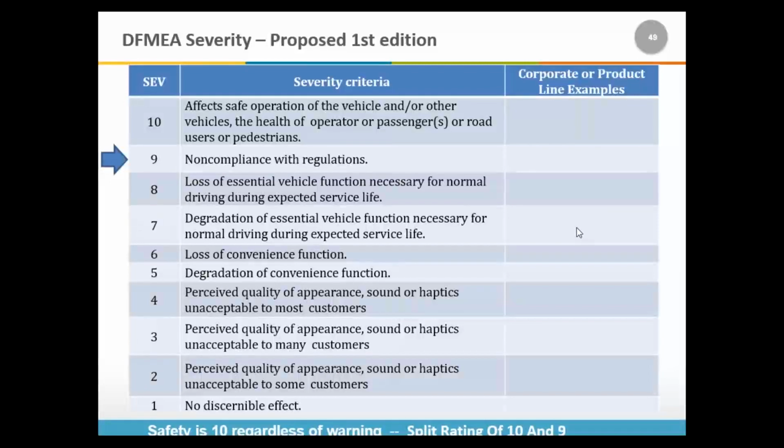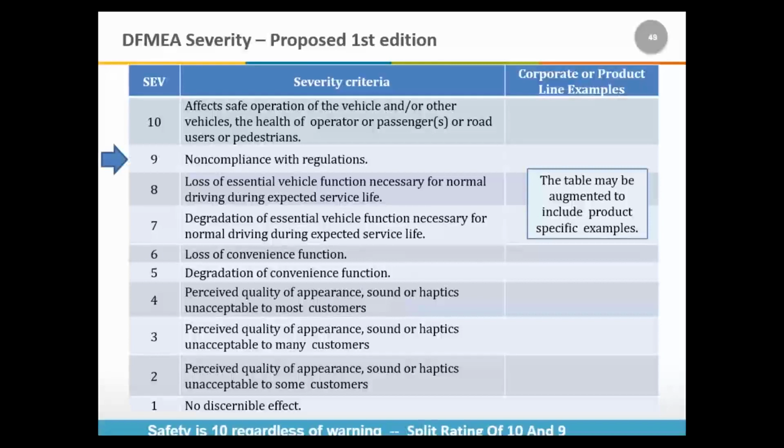Go ahead, Chad. Yeah, Greg, I think one of the points, correct me if I'm wrong, is that if you have a 9 currently in the AIAG DFMEA, it'll get revised to a 10 in the new DFMEA. Am I right in saying that? If it's safety related, the answer is yes. If the reason why you gave it a 9 was because of regulations, it would stay a 9. Okay, great.